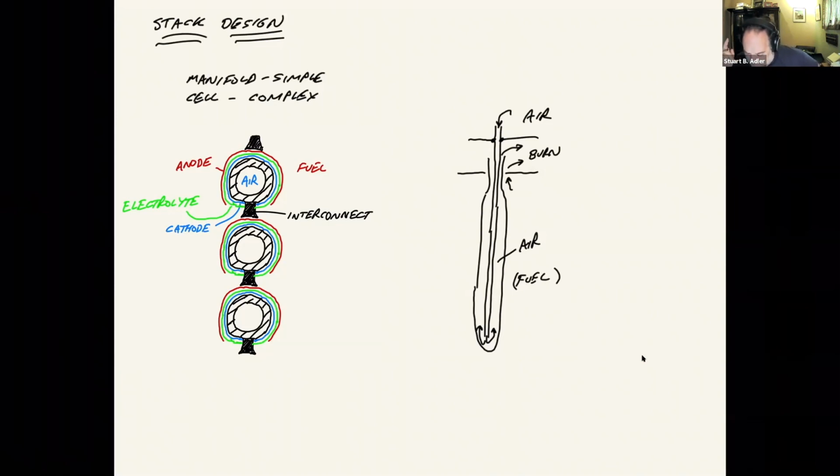The tube actually sits loose in its manifold because it's just connected to the afterburner. The only seal in this whole thing is where the air tube is welded to a plate. It's like a hole in the plate with a circumferential weld in it, just like a shell and tube heat exchanger. So this is the one and only seal in the whole thing,